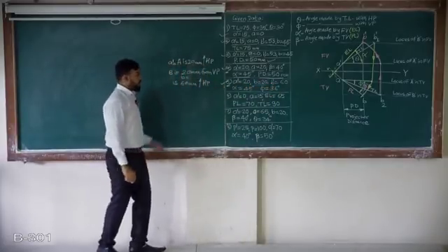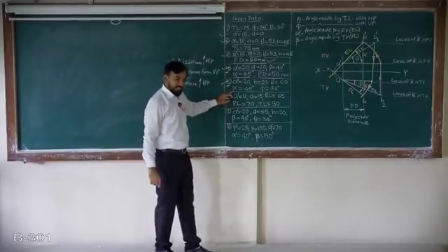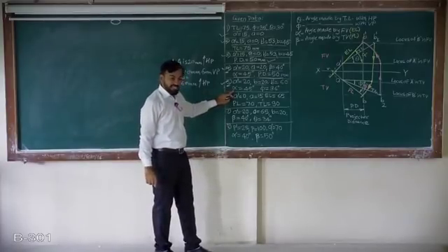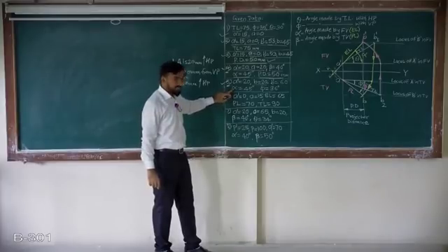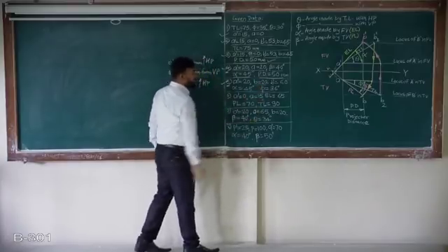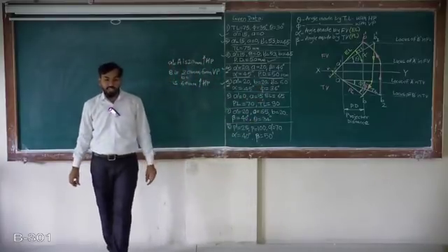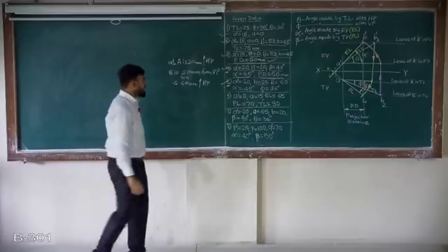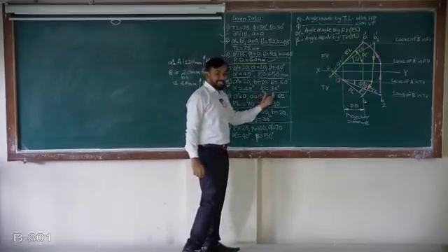Now the front view is inclined, or the elevation makes an angle. The front view makes an angle of 45 degree, that is alpha. That is given, and this is phi, meaning the true angle in the top view: the line is inclined to VP at an angle of 36 degree.